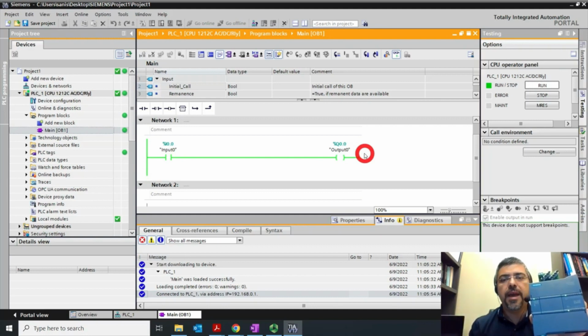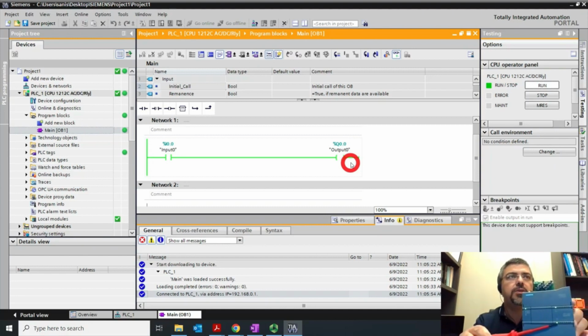If it's 1, back to the ladder logic, this is normally closed, so if it is 1, it should be closed, and the IO should be 0. So here you see the IO. See these little LEDs here. This line is your output. Okay, so this is output 0. That means 1 gives you 1. This is what you expect. Okay.